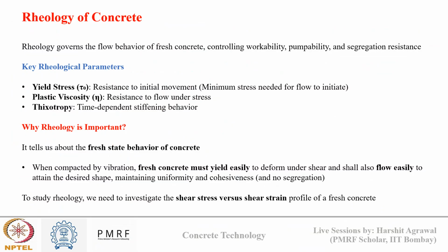Now, after packing density, we have rheology. Rheology is a fundamental property that governs the flow behavior of fresh concrete. Understanding rheology is crucial because it directly affects the workability, pumpability, and segregation resistance of concrete. Also, it helps us to determine how concrete behaves before it hardens, which is important to ensure that it can be placed, compacted, and finished properly.